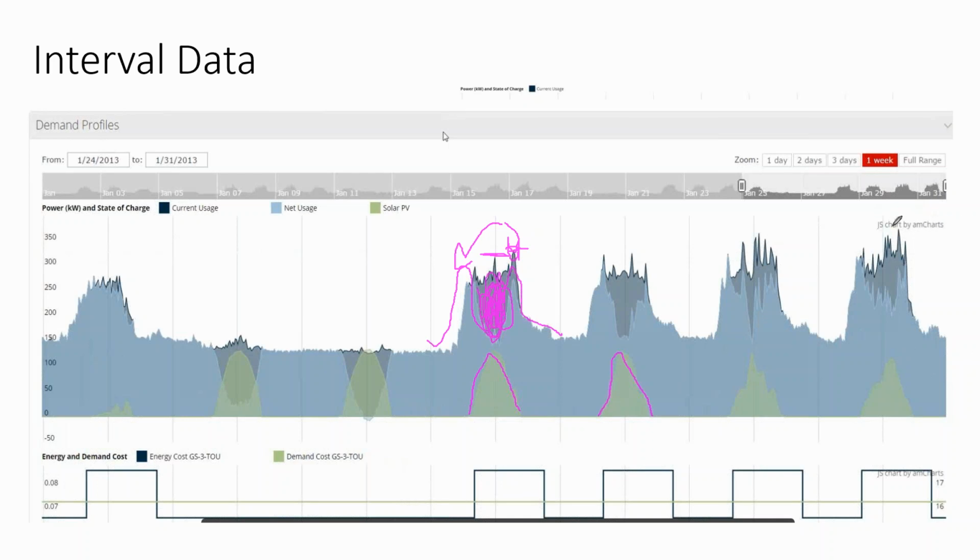The danger is you can say, okay, solar is going to take care of our peak demand, but as far as the peak demand charge goes, all it's going to do is push the demand charge into the solar peak. So if the solar array size is, say, 200 kilowatts, the demand charge savings might actually only be 50 kilowatts.